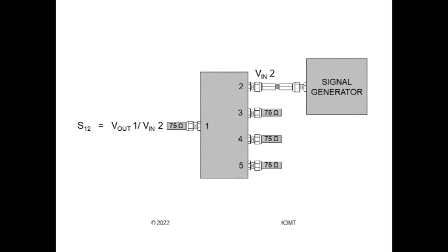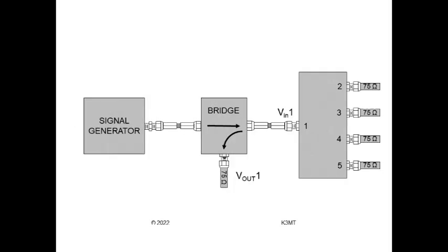A 75 mV input will produce 1 mA, in phase with the voltage. But, with some impedance imbalance, the current can be different. A separate 3-port network, an impedance bridge, can measure the difference. And let us measure the mismatch, a voltage reflected out of port 1, V out 1.